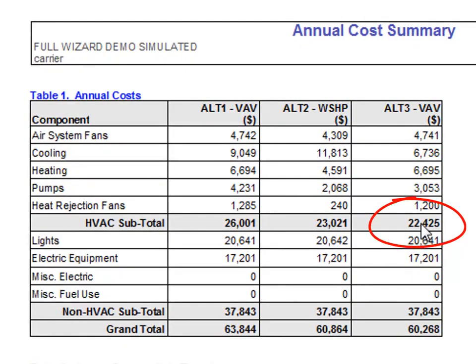Several features contribute to that result. It uses an airside economizer and a higher efficiency water-cooled screw chiller with excellent part load characteristics. Also, the fans are equipped with VFDs for airside savings at part load conditions.